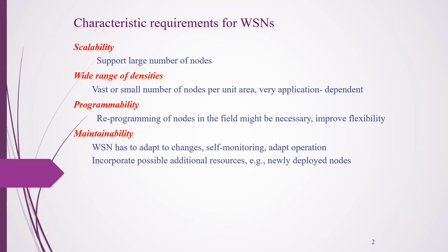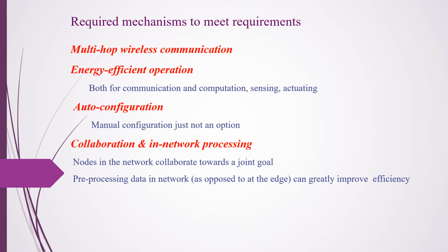The last challenge is going to be maintainability. As both the environment of a WSN and the nodes themselves change, we need to monitor the health and status of the operational parameters and choose different trade-offs. When the energy source becomes scarce, the network has to maintain itself and be able to interact with an external maintenance mechanism to ensure extended operation at the required quality. We have seen various challenges about the WSN.